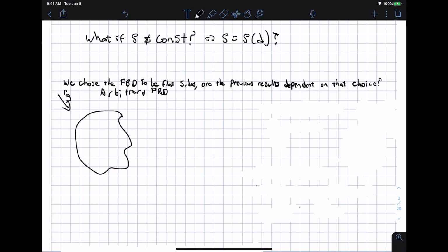free body diagram. Okay, and so we have some net mass times gravity here. So we have a net weight, and on the surface of it, we have pressure pushing against the surface, again in the opposite direction as n hat. On the surface, we have an element of size dA here, and we have a differential pressure force pushing on the surface. So we'll have a net pressure force that we can find by just walking around the entire surface and integrating all the pressures on all these little differential patches.